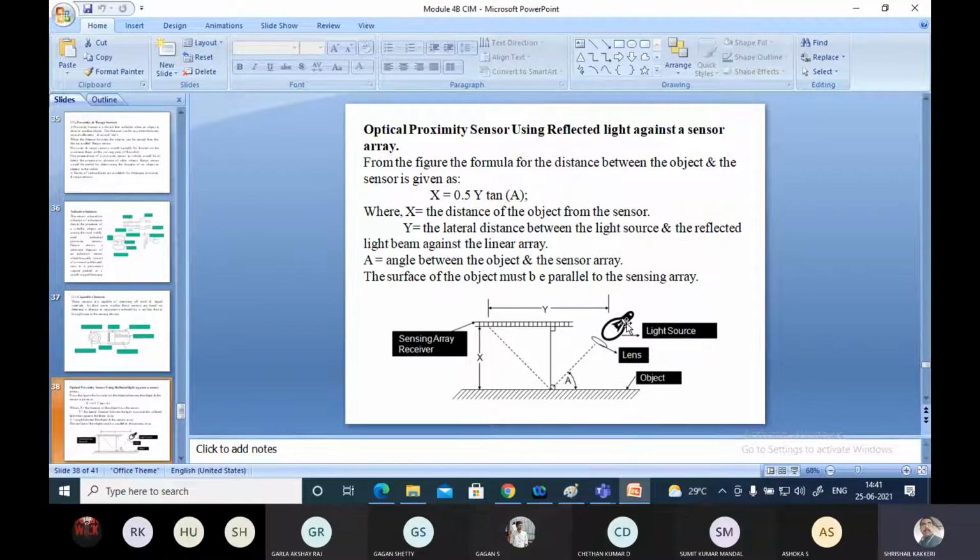Just like I am throwing a ball from here, it will bounce from this and go to the other wall. So there will be a trigonometrical relation. You can say this x we know and this y we know, and we are able to find out the length. That means the algorithm developed in these sensors is able to measure the angle of the reflection, and this angle will be a measure of distance. You can see that the reflection is 30 degrees and it has already been fixed at 30 degrees, correct?